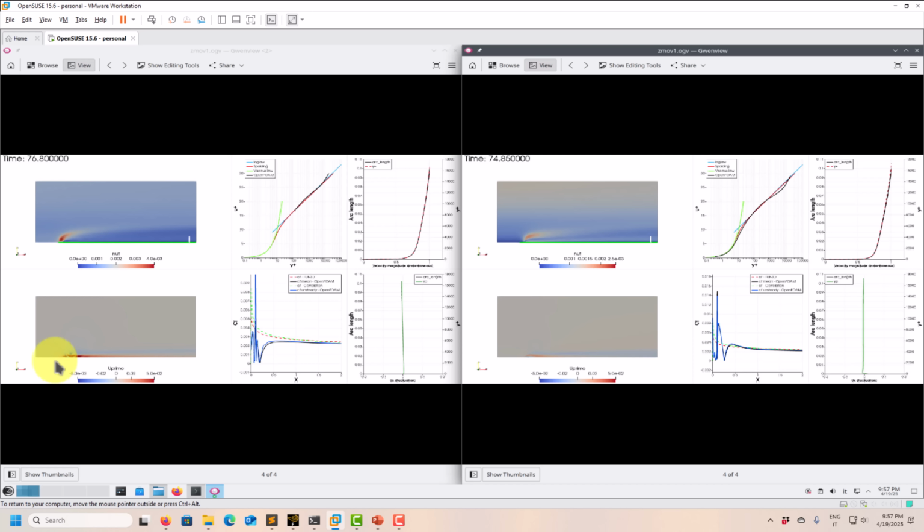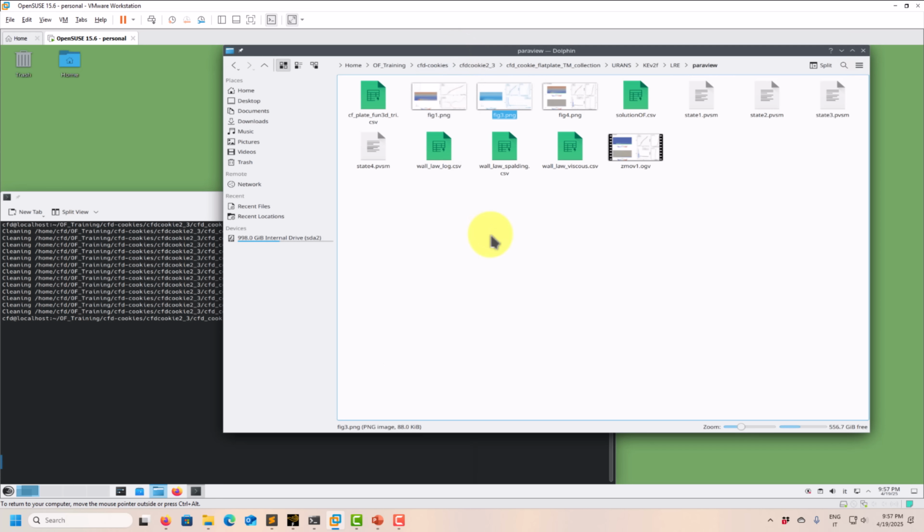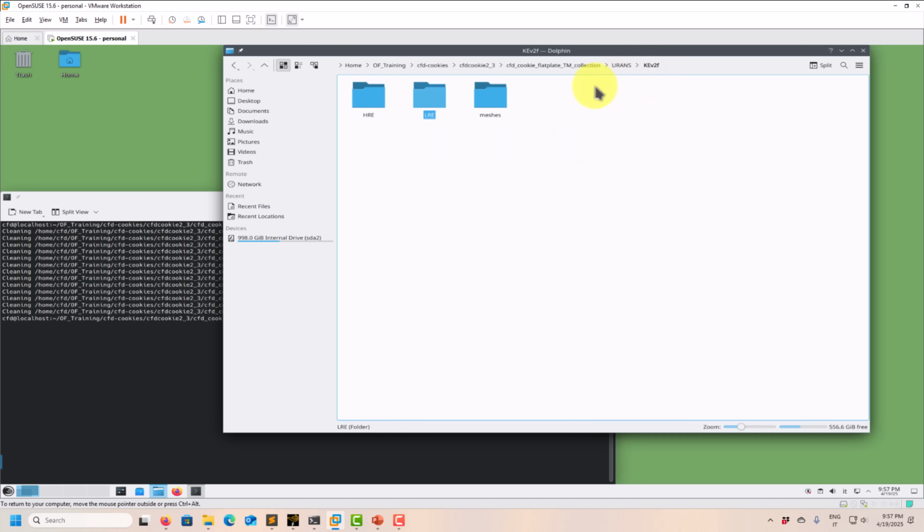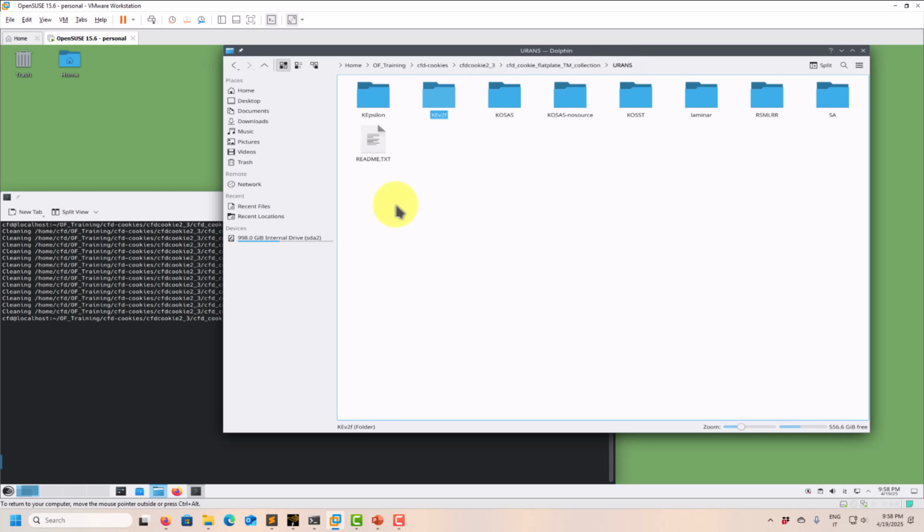Well, every different turbulence model and every different treatment at the wall. And look at that, all this diffusion that we're adding, this effect is not seen anymore, and we're matching our theoretical value very well. Now the low Re, instead, this one has some differences. Probably if you let it run, you will get good matching, but there you go, okay? So V2F, a model that I really like, does not behave very well in this case.